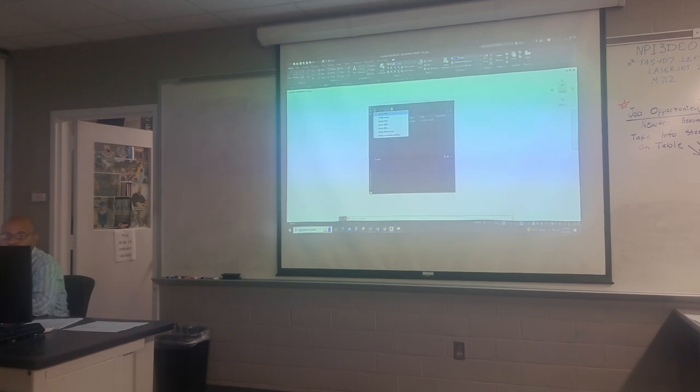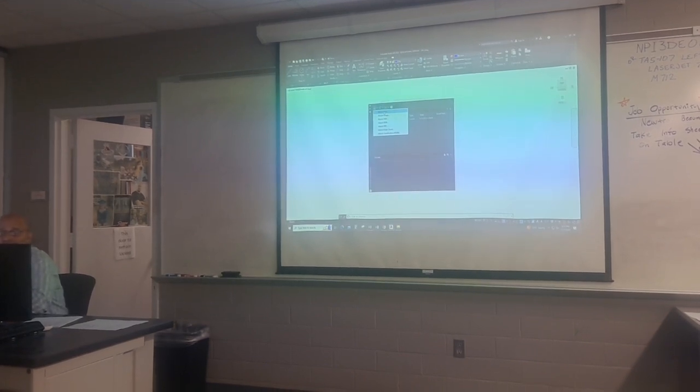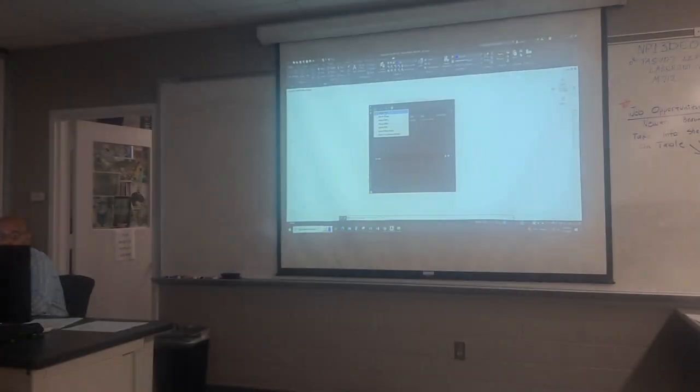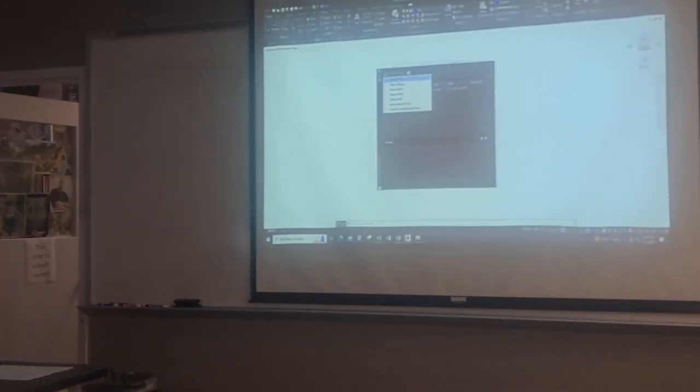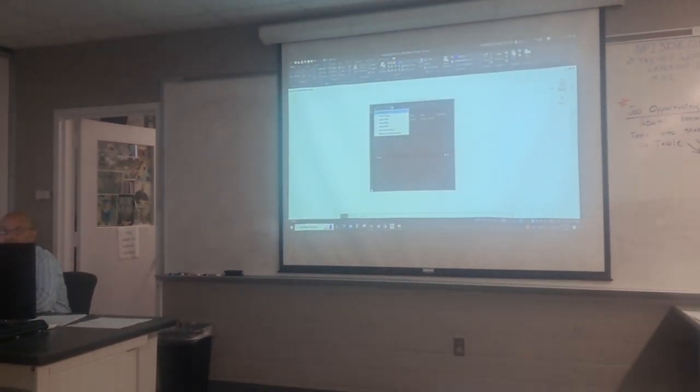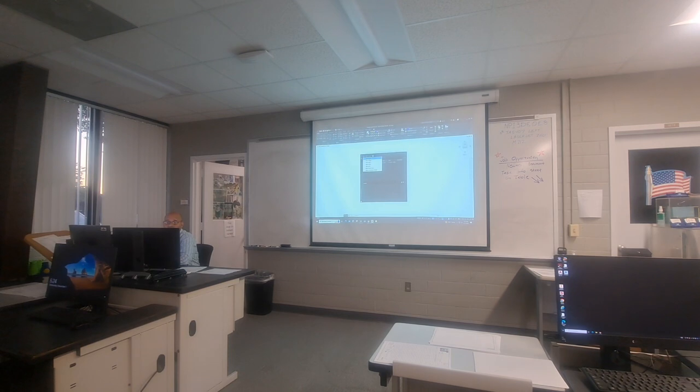Yes. So what I can do is pull this down right here and I can attach different types of items. I'll show you also later on today how to bring in other things like images, and we don't go through this XREF process. But to do it with the full XREF plan, to bring it in as a watermark that we can't really modify, that's what I'm going to show you, which is what would be done in industry.